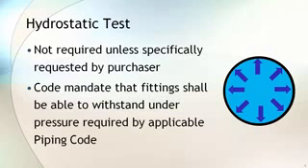Hydrotest is not required unless specifically requested by the purchaser. The code mandates that fittings shall be able to withstand the pressure required by the applicable piping code. Most purchasers mandate that hydrotested pipe shall be used to manufacture the pipe fitting.